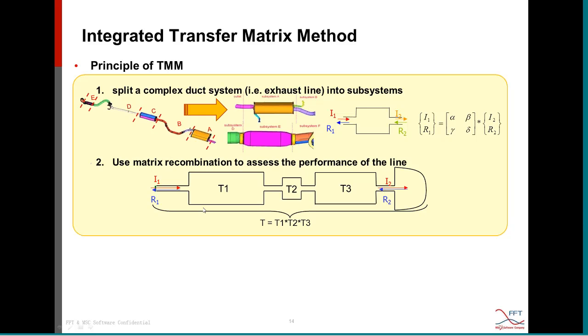We can also introduce the real source at the inlet. For example, we can provide a source amplitude and a reflection factor at the inlet, and apply an infinite element at the outlet to calculate the free field acoustic propagation.